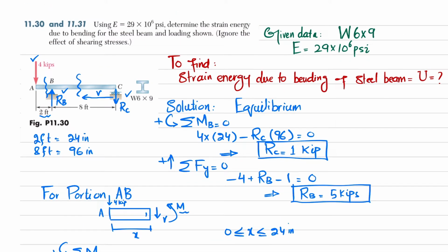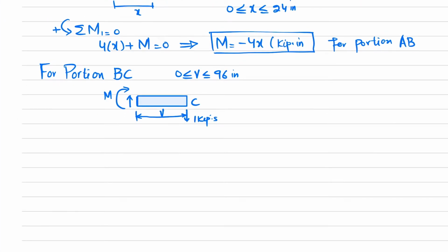I will show you. We start from here, v is equal to 0, and it goes till point B. This is 8 feet, which is 96 inch. Okay. So again, let this be point 2. So the sum of all moments about point 2 is equal to 0, taking counterclockwise moment as positive. You can see at point 2, the moment due to 1 into perpendicular distance v is clockwise, and we have another moment that is also clockwise. So their sum must be equal to 0.